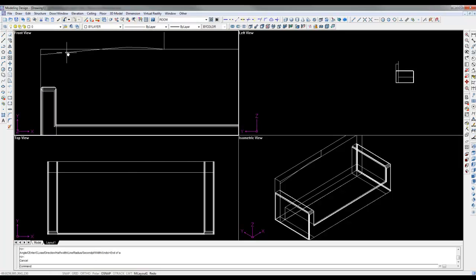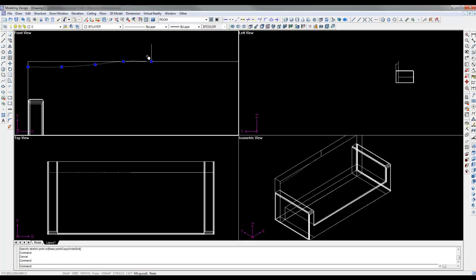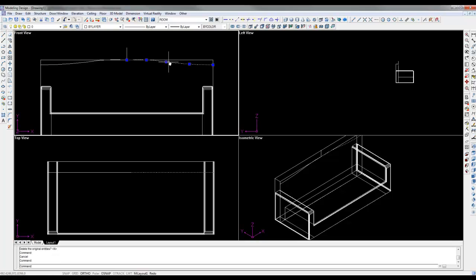Okay. And now I can just tweak those little handles over there by just adjusting the little points. And I'm just going to drop this down so we can line up with the height there. And that should be okay. Just make that a little bit lower. Okay, so now I'm going to just mirror this. So MI for mirror again. And just give it a straight, my ortho on. There we go. Enter. So I've got 2 pieces now.